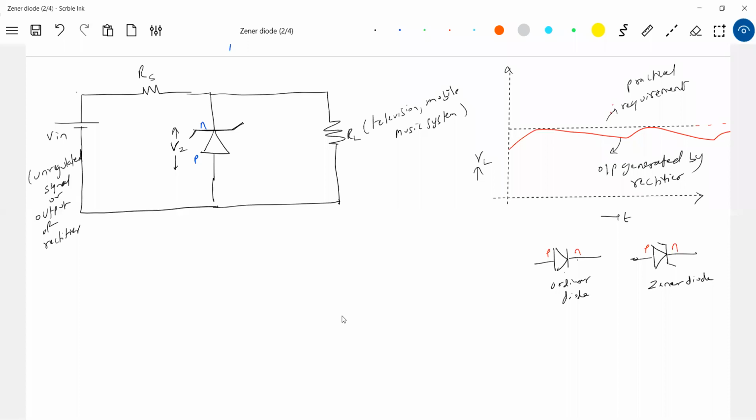So what is the basic idea of the Zener diode? I'll start directly with a problem. The breakdown voltage. Let me take a numerical, because if I talk, it will become like a story, and you'll get a good sleep. So let me assume these values. VZ is 10 volt, RL is 100 ohm, and RS is 200 ohm. Okay, this initially has a voltage of say 40 volt. Initially let it be 40 volt.